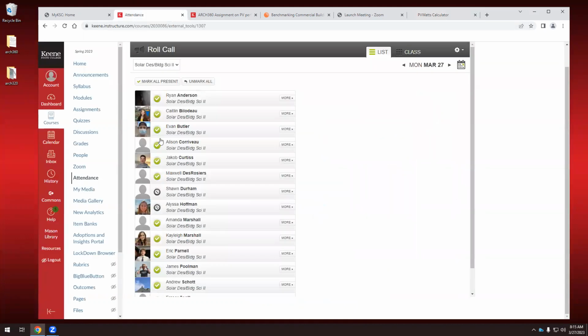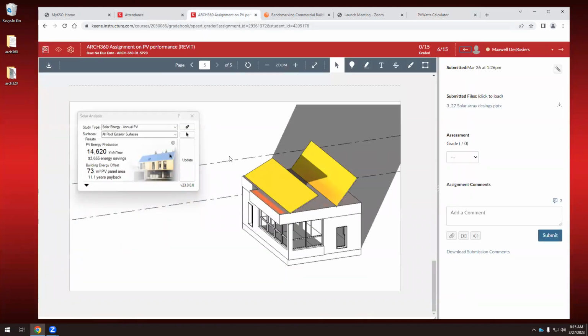In Revit, we can create a 1-year simulation, and you see that there's a different color here. That means that for part of the year, this array is casting shadow on the other ones. So that's why we have different colors here. Every time we cast shadows on this, that panel stops producing energy. It's not that it has half the panel in shade, so it produces half the energy. No, it produces 0. And that's something very important.